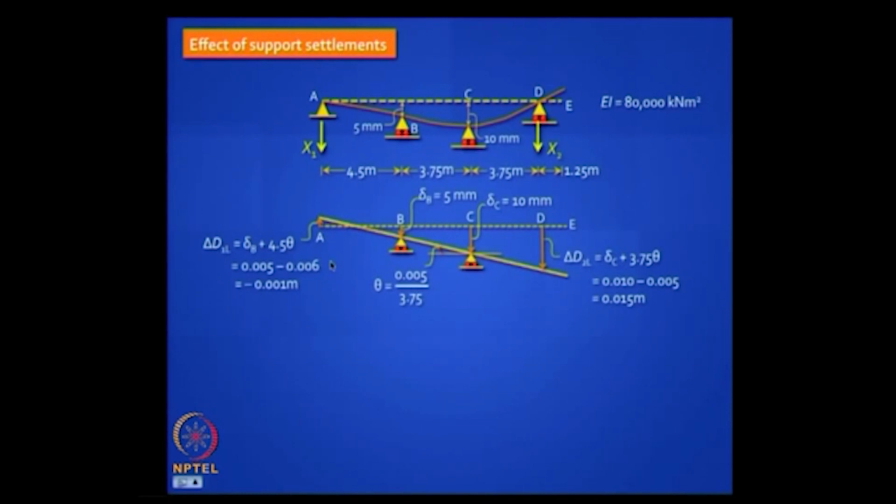You need to use that to figure out those two movements, which is simple. You can easily do it using logic and get the two deflections correctly with the proper sign. You will find that delta d1l turns out to be negative, whereas delta d2l turns out to be positive. If you made a mistake here, you will get wrong answers. So you have to get this correct, and after that same old equations.